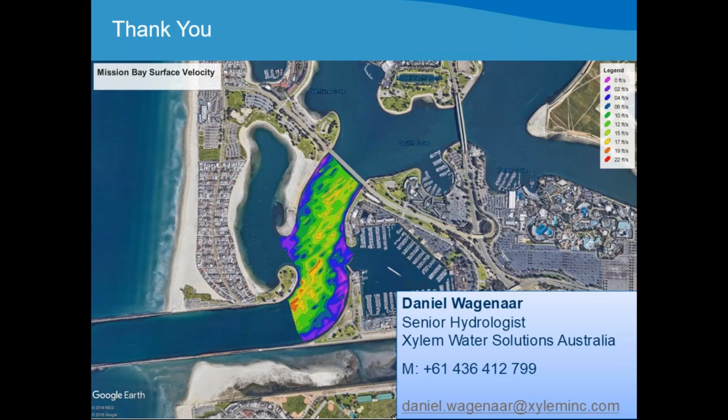So one way of finding this out, and we haven't discussed it in this webinar, is to look at your SNR profiles, signal to noise ratio, that's displayed in real time. And if you see one, two or even more of the beams separating from each other. So normally the SNR profiles should be closely matched. They're not going to be exactly the same, and depending on the profiling technique, if it's pulse coherent or incoherent, pulse coherent is a bit more noisy because it's smaller cell sizes. Incoherent is a bit more faulted because it's larger cell sizes.